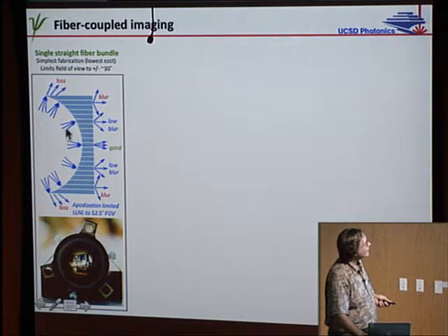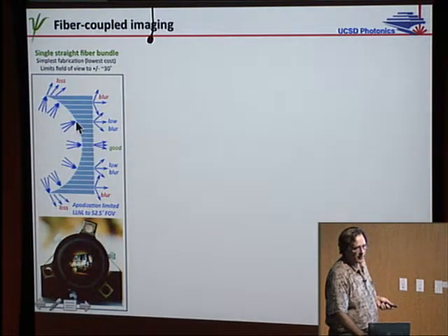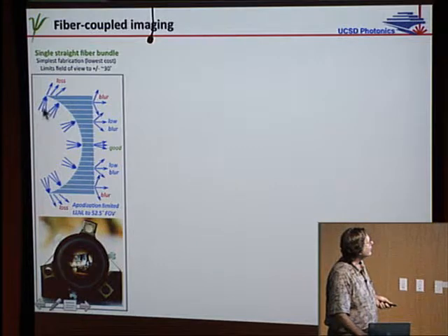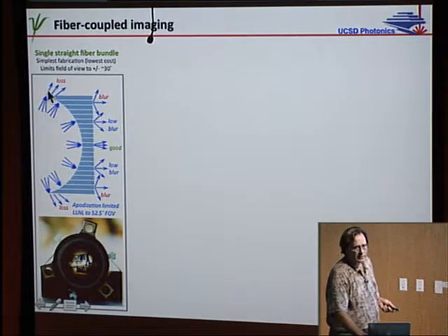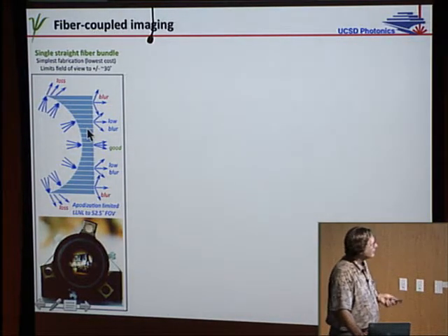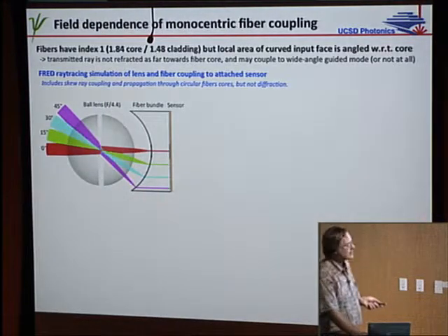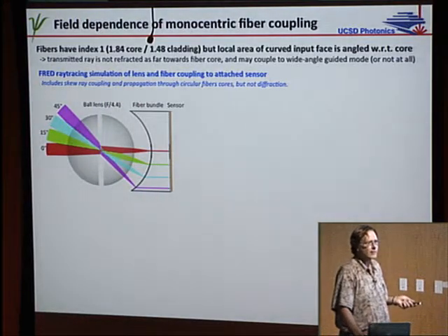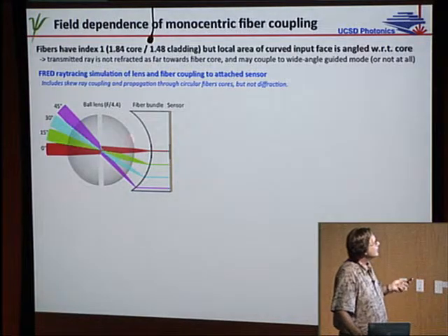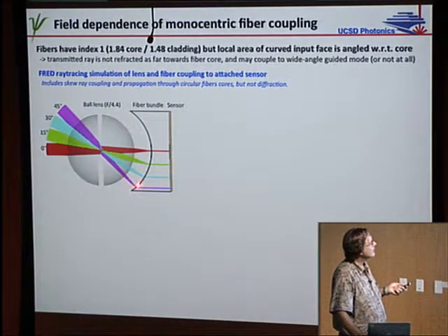And if you think about how waveguides work, then you're really not getting that refraction that makes you guide. And at some point, of course, you're going to go right through the sidewall. And it turns out that that's what limits this. You can model it. It's actually a harder problem than you might think, because you really have to look at skew rays and diffraction and all kinds of stuff. But you can get a pretty good model using Fred non-sequential analysis.